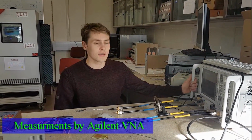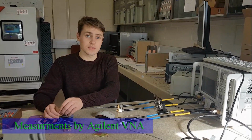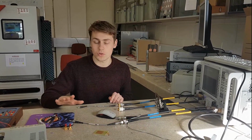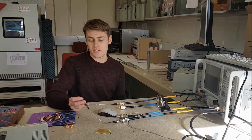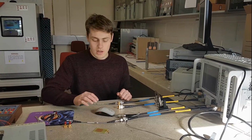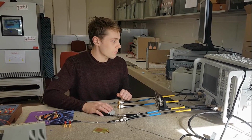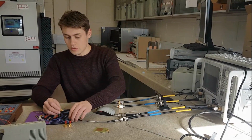Now we're going to perform the same measurements but with a higher spec VNA. We've got an Agilent VNA just here. I'm going to first calibrate it once again using the same method with open, short and load ends. This here is an APC 3.5 female connector. I'm just going to be following the calibration wizard to get this set up. Firstly, I'm going to connect the open end.